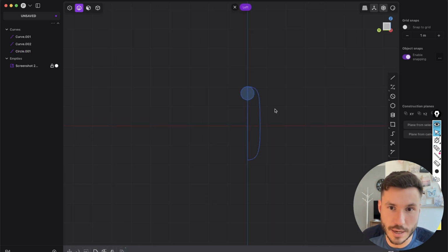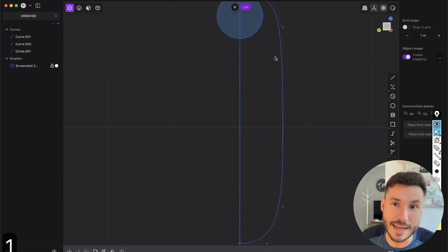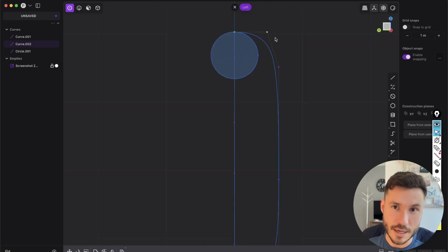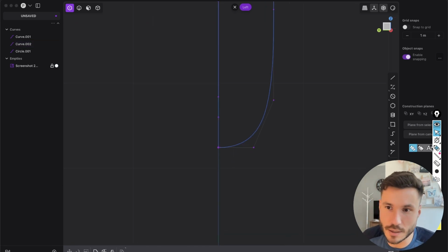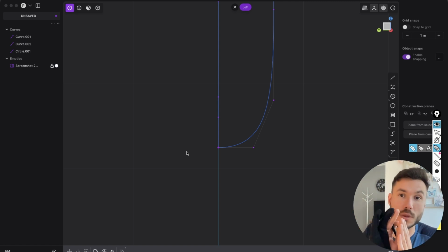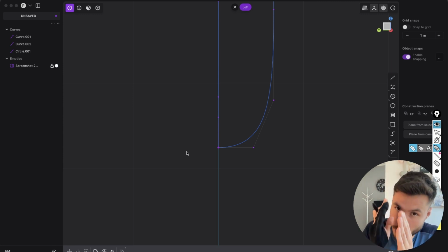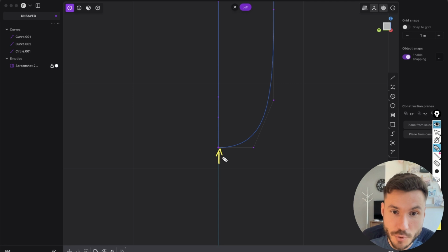So we can again just apply this now to our curve. So go to the left view, press 1, and now we can just adjust those points a little bit. And remember, this first point and this last point has to be tangent. Because again, as most of the time when we do product design, we just work with a half because we will just mirror that over. But to mirror it over and to have smoothness on the middle edge, we need at this point tangency, so G1. So that means that those points have to be on the same plane, right? Because if we just mirror that, then our blue curve will go like that.